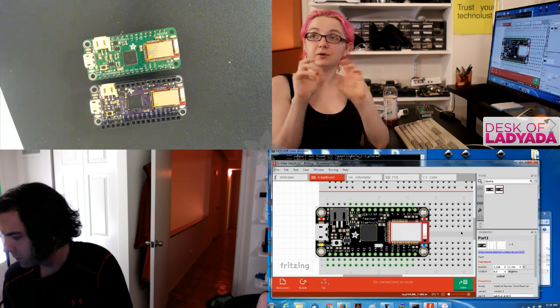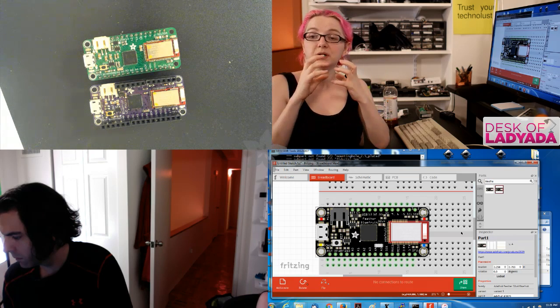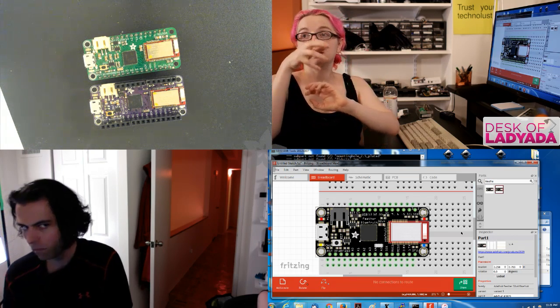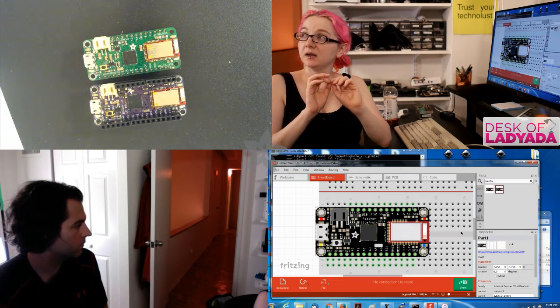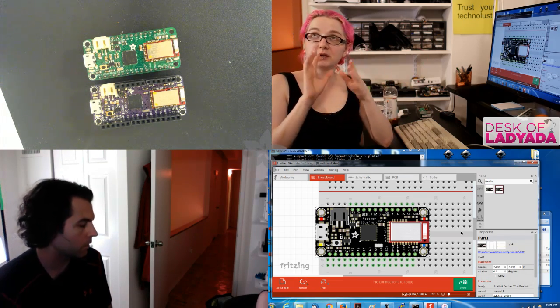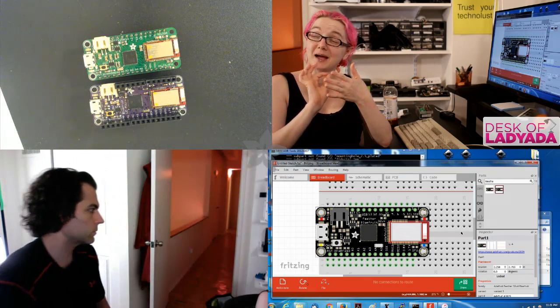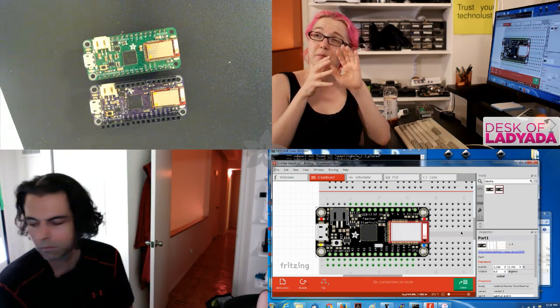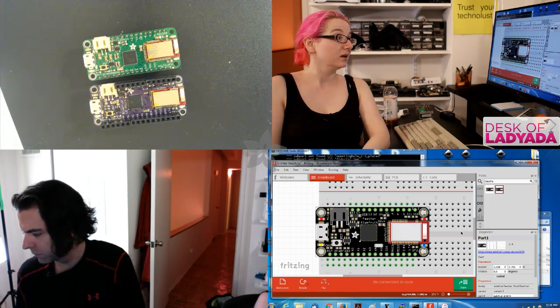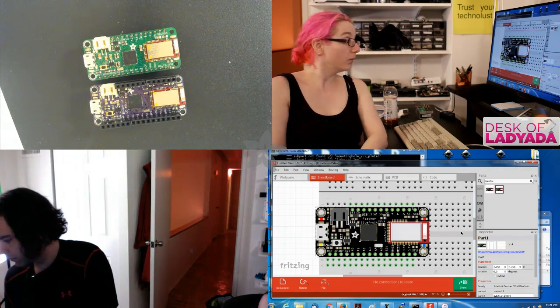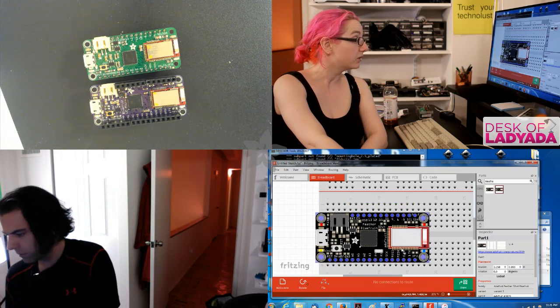It's not hard if you know how to do it, but you have to group the parts in subgroups in the XML. The XML has to be perfectly formatted. One time this generated a file that the SVG was not exactly perfectly formatted. There was a part sub element that was misnamed, and Fritzing just exploded all over the place. So that took us like 2 hours to figure out why. But when we figured it out, we're like, oh, okay, it's not too bad.